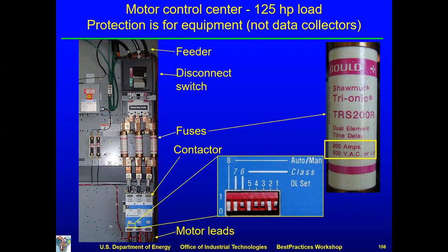It'll give you the power factor. It'll give you everything right there if you have a real power meter. If you're too cheap to buy a real power meter, you buy a voltage meter and you record the voltages, the phase to phase, and then you clip on this one, this one, this one, and you just get amps, and then you get voltage. You average all that together, and then you have to guess a power factor if your meter can't measure it. And that's always a challenge. We'll talk a lot more about that. But that's what you mean by 3-phase power.